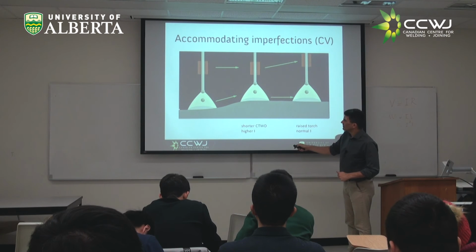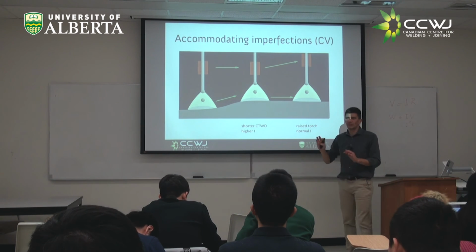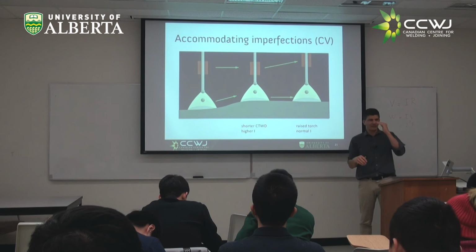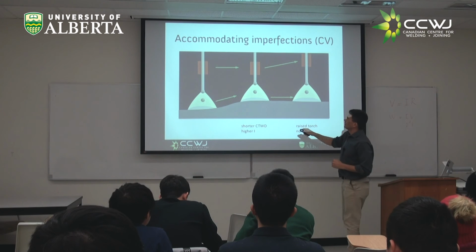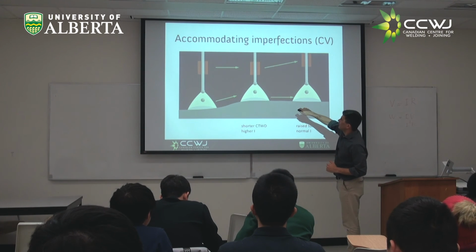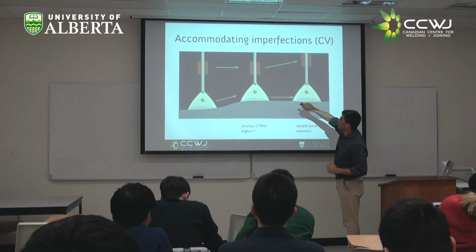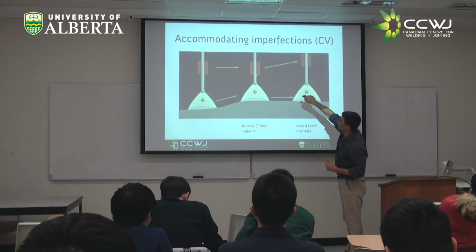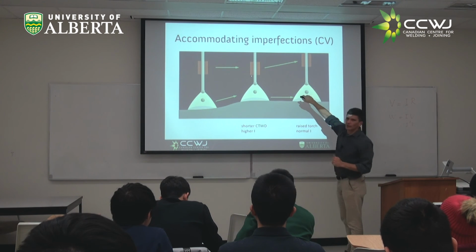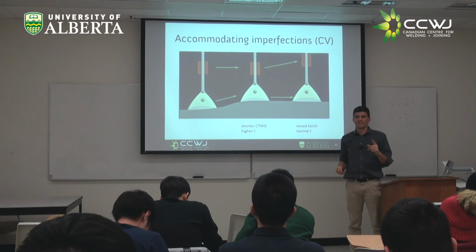So if all of a sudden your plate is bent, undulated, or something, for whatever reason, the plate that they promise you is perfectly flat. It never is perfectly flat. Now, the plate is taller, and what would happen? Because you keep more or less the same voltage. You told the machine to keep the same voltage. All of a sudden, you have a shorter electrode stick out. Current is higher or lower?